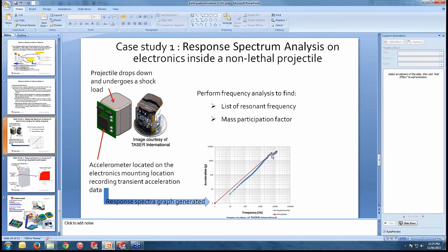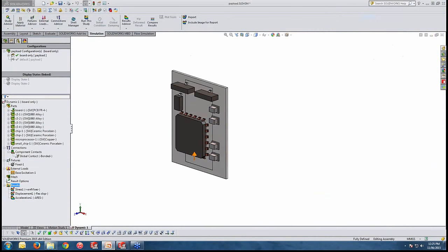It goes through around 3,500, and the frequency according to this is around 5,000, and it still remains the same. What we need to do is to simply say acceleration is going to vary with frequency by that curve, the red curve. So, reading the data correctly, go back to base excitation, edit definition.